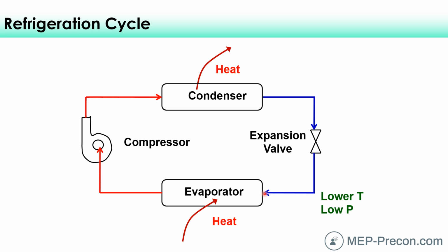So within a heat exchanger, there are two fluids, and one fluid is going to heat up and the other is going to cool down, because heat transfer happens through the walls of that heat exchanger. In this case, the return air within your HVAC system, if it's warm, might be about 80 degrees. It heats up in the room, comes back through the return duct, and goes into the unit. It might be about 80 degrees, and the refrigerant coming in here is about 30 degrees.